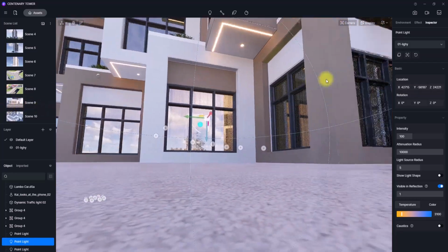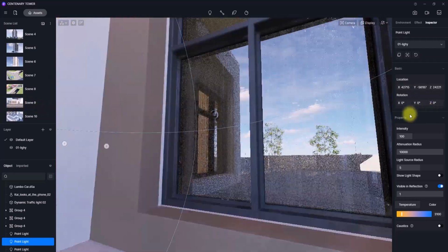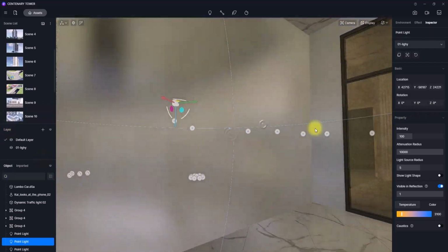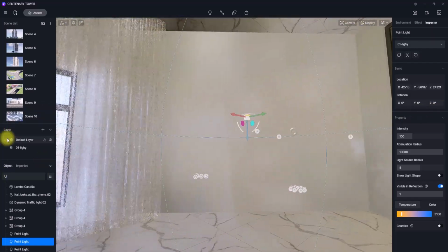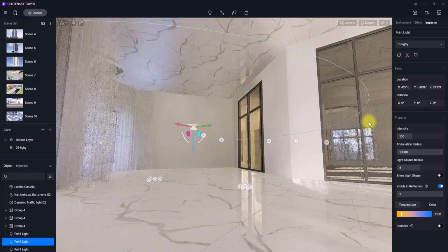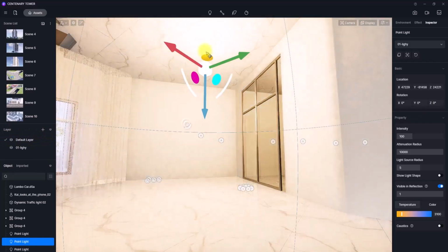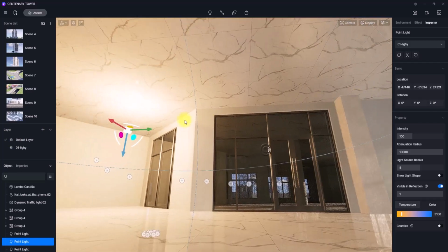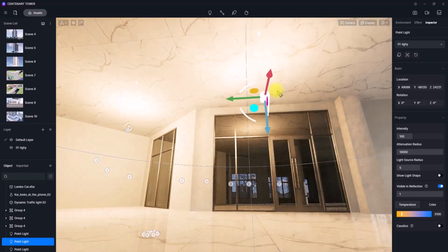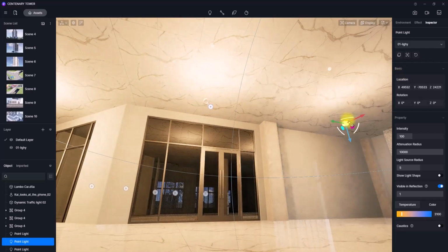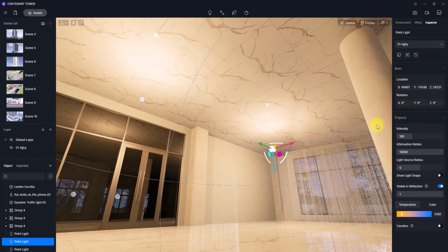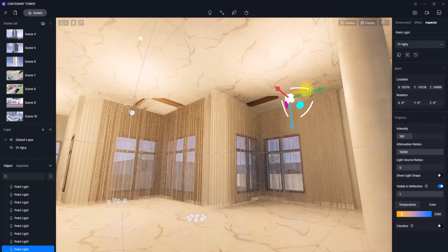If you are wondering why I created the lighting layer, it is simple. When I want to render daylight views, I could easily turn off the lighting layer, so all the lights will simultaneously hide. It will give the daylight feeling, a full daylight view, without the need of manually hiding all the lights yourself, or even at worst deleting them.